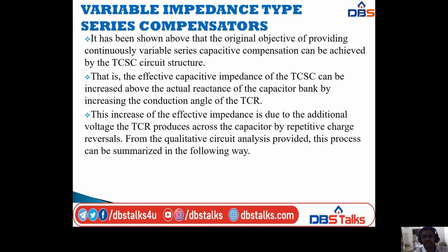That is, the effective capacitive impedance of the TCSC can be increased above the actual reactance of the capacitor bank by increasing the conduction angle of the TCR. This increase of the effective impedance is due to the additional voltage the TCR produces across the capacitor by the repetitive charge reversal.